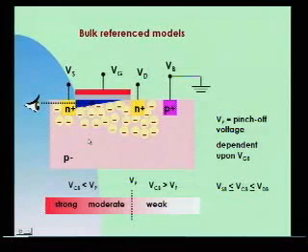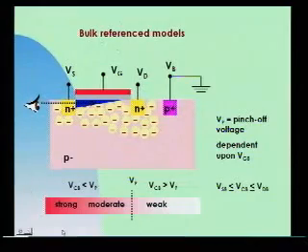Surely it is arbitrary because the transition is smooth, but the pinch-off voltage can be said to be the value of the channel voltage that separates the channel into a weak inverted part and a strong inverted part. Okay?